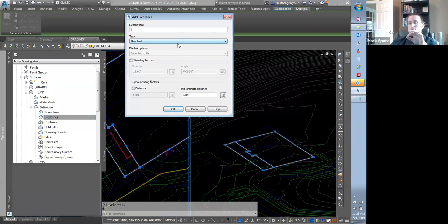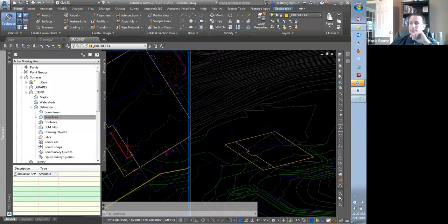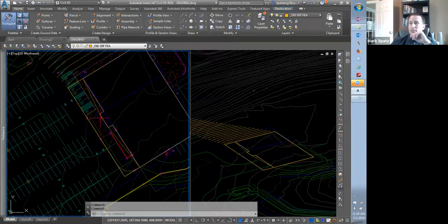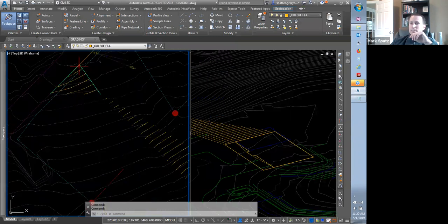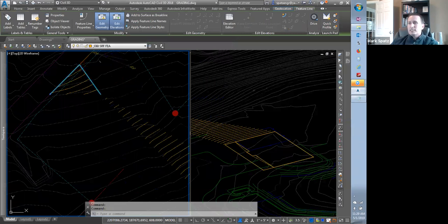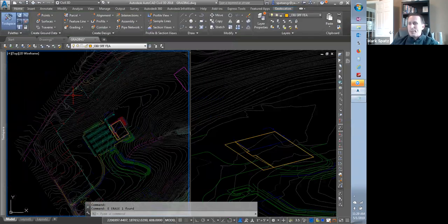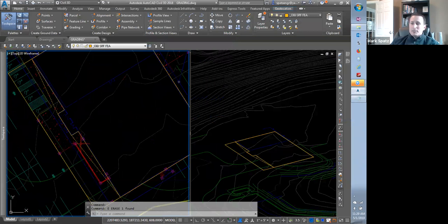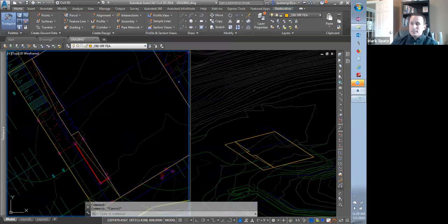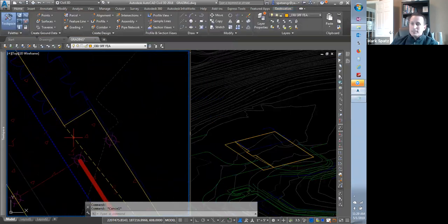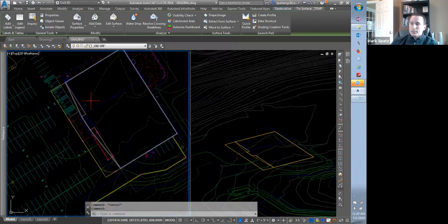So you always go into Q, select first, select the whole layer, then you just go under break lines, hit add break lines, you just hit OK. And that will make our reference surface. You can see it must have grabbed some, I got some stuff down here. Delete that. There's not much in it because it's just the first floor and the face of curve, but you can see it did draw one contour.